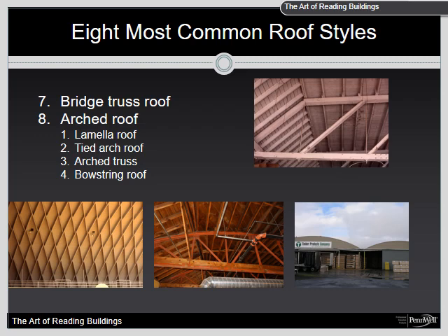Hazards. While the arch trusses have more inherent rigidity and stability than other arch roofs, they are still susceptible to collapse. All steel rib arch trusses are much like other steel trusses in that they are prone to rapid heating, especially if the bottom cord is exposed to burning contents. Steel rib arches will try to elongate when heated. Arches that sit in wall pockets will try to push out the exterior blocks or bricks where they are attached. A collapse warning sign.